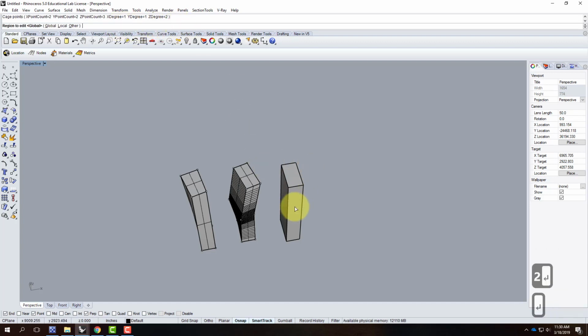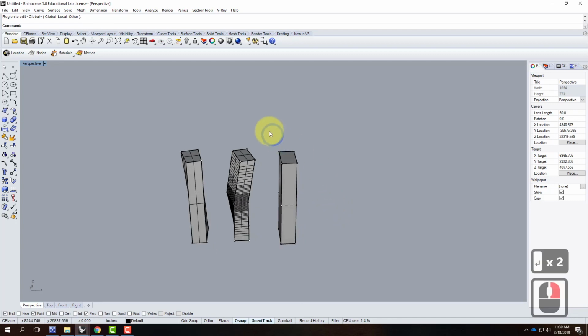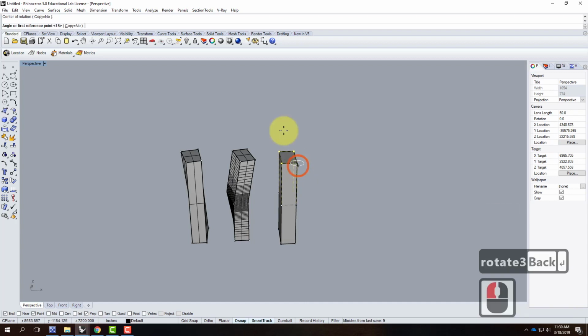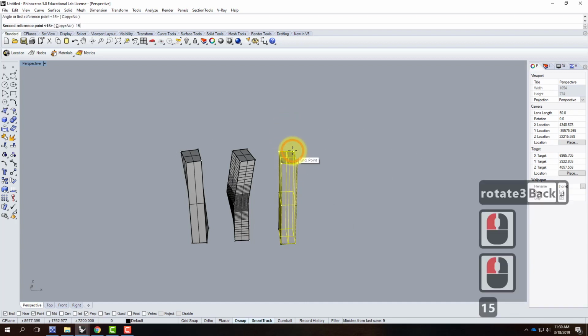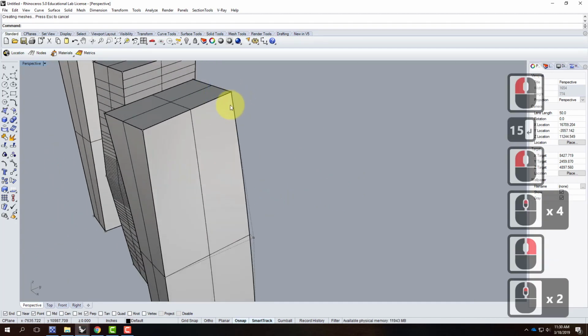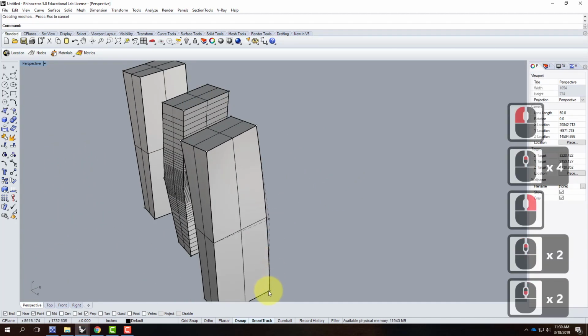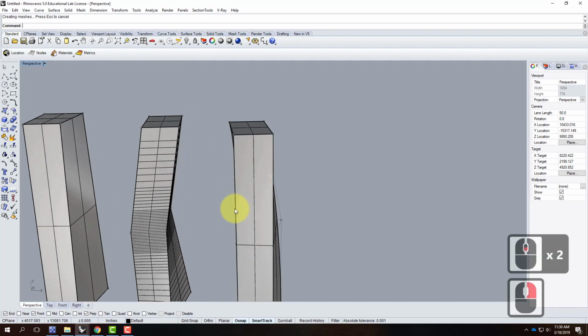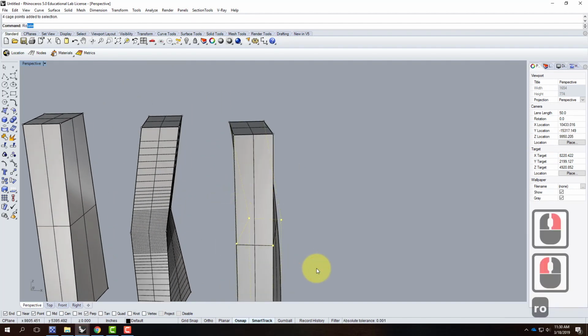Watch what happens. There we go, global. I'm going to do the same rotate where I take this top and I rotate it. Right from there. And that's going to be 15 degrees. Instead of being a straight line from here to here, it's actually arcing all the way through my object. So I could take this middle section and I could rotate it the opposite way.